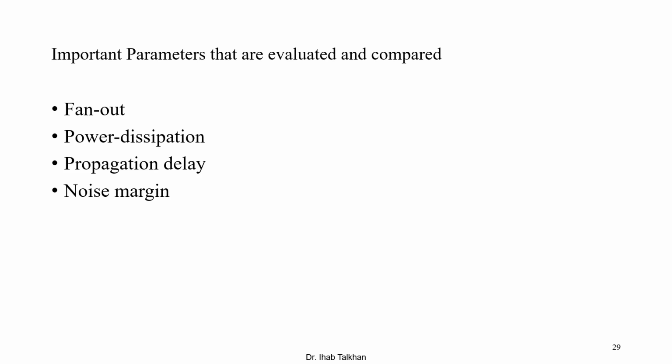Fan out actually, if you are having some output and you want to distribute this output among more stages. I mean, you want to feed other gates, not only one but more than one. As if you have here at home, you have the electricity outlet from the wall, and sometimes you use what's called the electrical distributor unit. With this one outlet you can feed more than one device in order to have them all working from the same outlet.